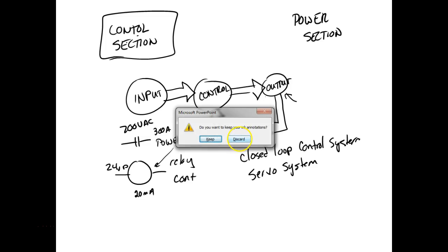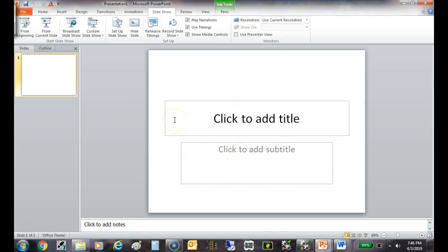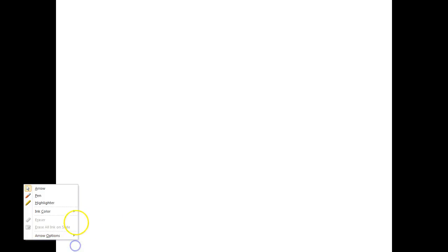Anybody know how we control the direction of a DC motor? We change the polarity on the rotating part. We call it the armature. And we usually do it with what we refer to as an H control.